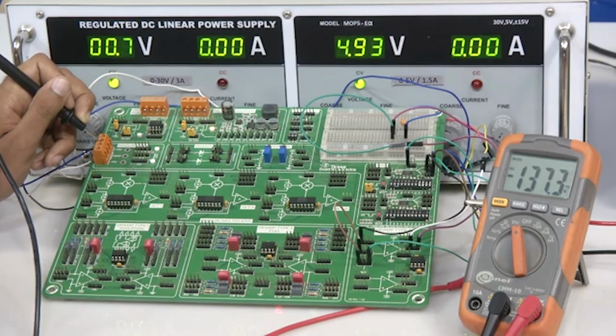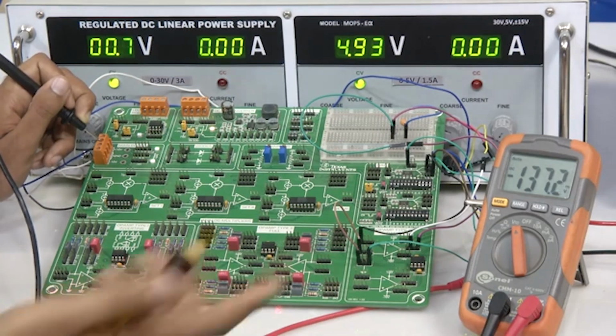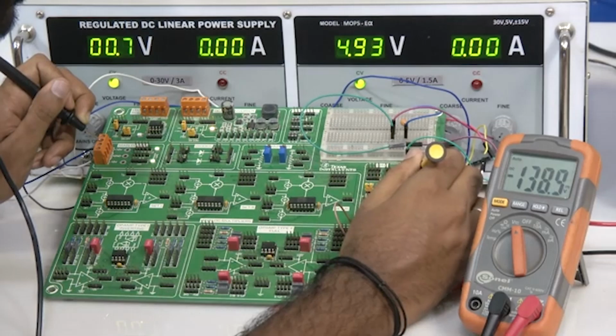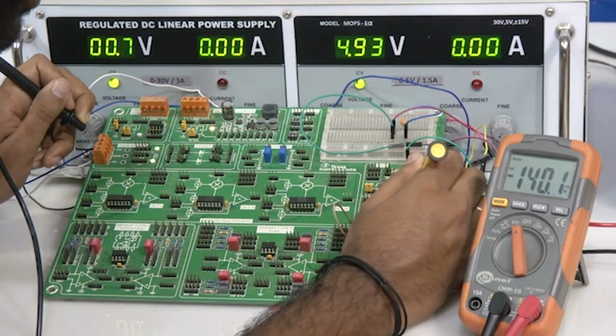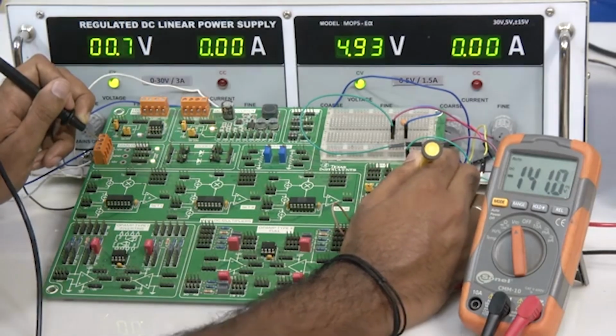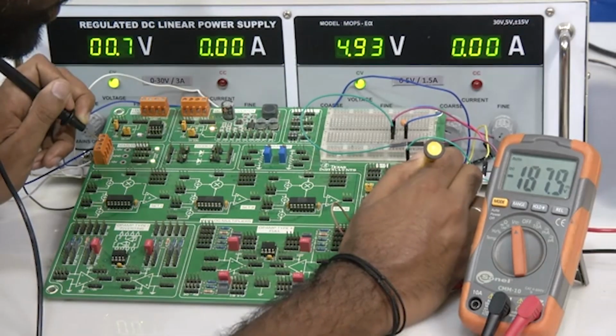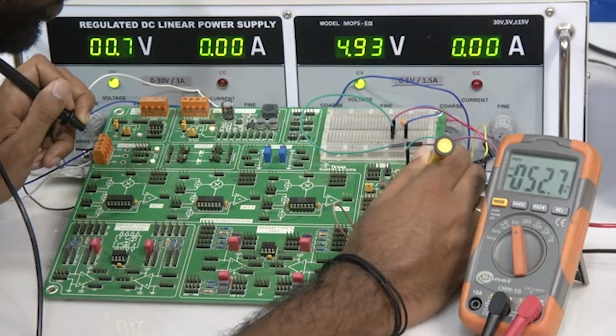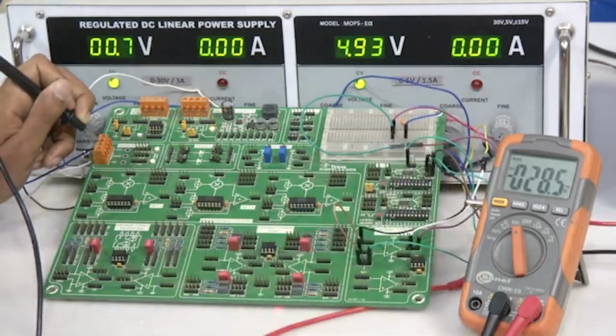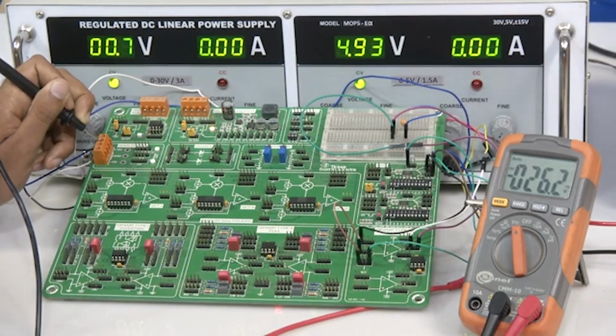To make sure that this is working properly, let us go back to our ground state. So I will make these D3, D2, D1 bits 0 and then retain the D0 bit as high. So we should go back to something around 26 millivolt. Yes, we have gone back to 26.2 millivolt. That means that the circuit is working very robustly.